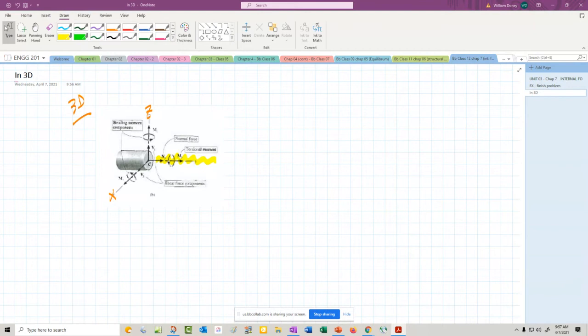The moment in Y is more torsional, meaning it's sort of twisting, like twisting of a bar. These others are just normal bending moments. And they all act at the geometric center, or centroid, of the cut face.